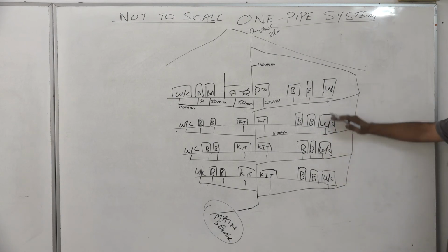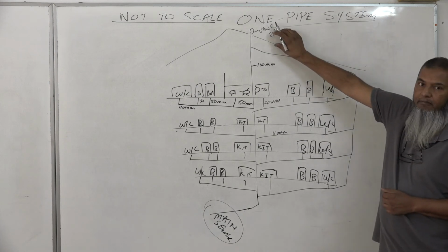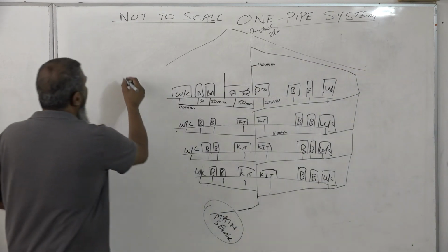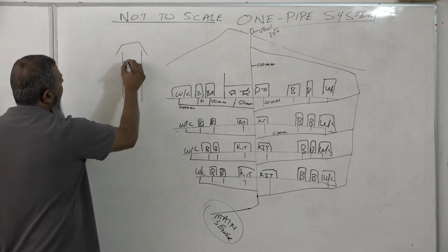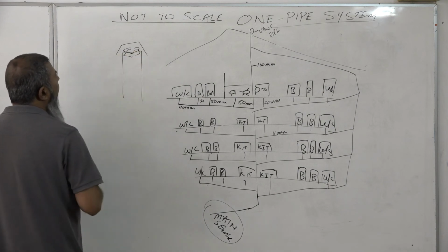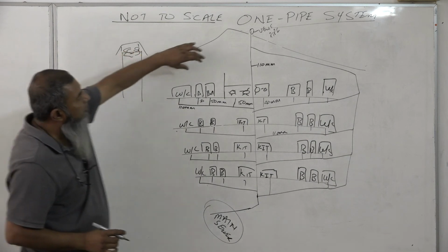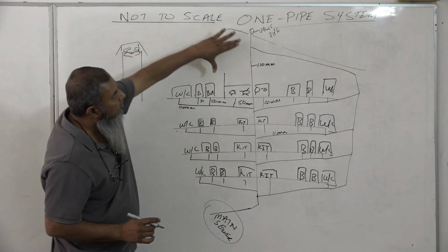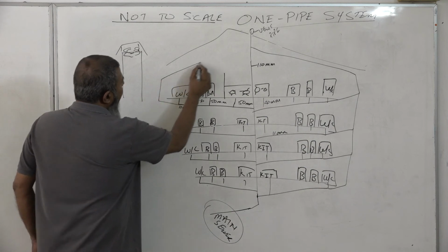So each floor of flats, or each block of flats, is venting to one common vent pipe. This vent pipe on the top looks something similar to this here. 110 mm pipe. It has a cap on it. Inside here we will normally place some wire, or they put a vent on this. So only air is allowed into this pipe. It flows right through, so there is no contamination of the water. On your left hand side as well, the same thing would apply.